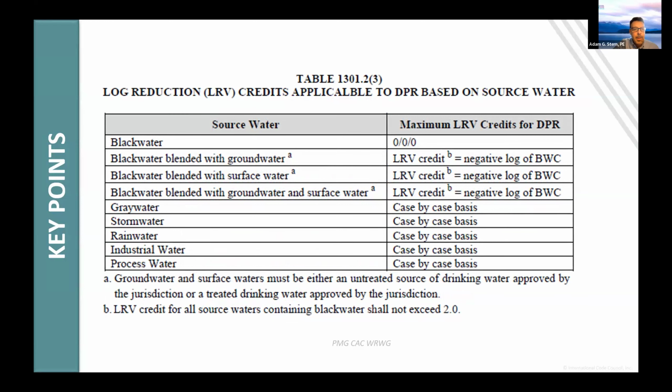And here I'd like to start at the bottom. Why do we not have a specific standard for, say, processed water or rainwater? Well, we essentially know the expected components of domestic wastewater, but processed water and rooftop runoff, at least after the first flush, can vary very much.